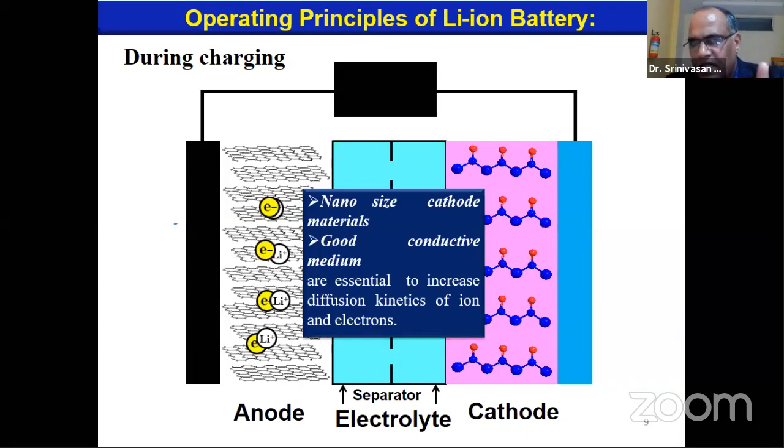Another important thing is that the battery chemistry plays an important role. Whatever material has a high voltage, you will always get a high energy density, and that will reflect in a long driving range. But again, there is a trade-off. If you go for a higher voltage, you have to compromise the thermal stability and you don't get that long a cycle life. You have to play with the battery chemistry according to your application.